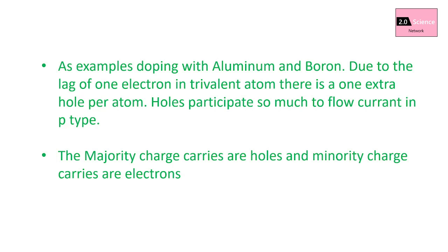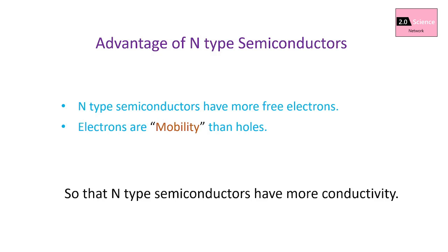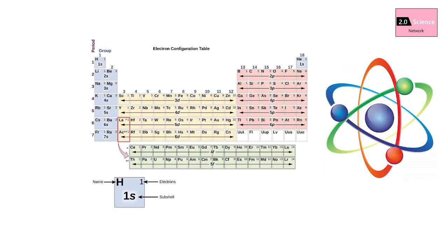Among these two types, N-type semiconductors have more conductivity, because they have more free electrons. Usually, electrons have higher mobility than holes, so N-type allows current to flow quickly. The major advantage of extrinsic semiconductors is that there are more electrons or holes in the material. I added only one pentavalent atom electron, and more electrons slip due to increasing temperature in the animation. But you must remember, in real-world conditions, a relatively small amount of electrons slip due to temperature.